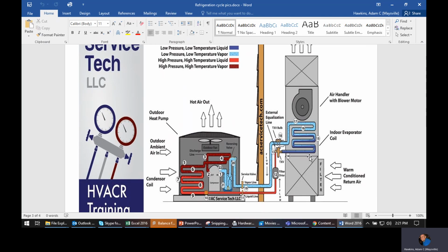It's really hard to believe that a cold line can hold all that heat, but as we've mentioned in class, that just shows you the capacity that refrigerant has just by changing states. So even though that line can be so cold it's sweating, it can be 50 degrees, it still has all the heat because it went through that latent change.